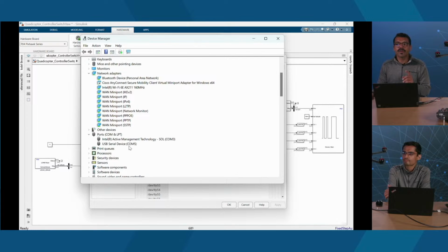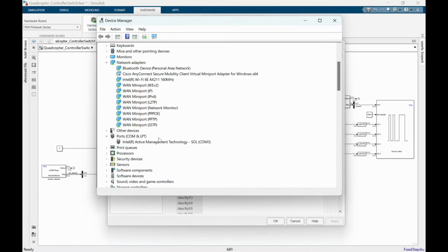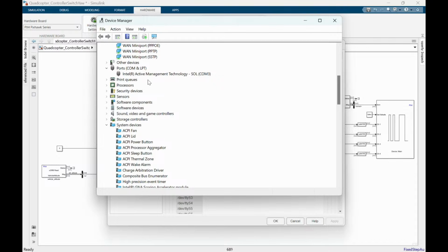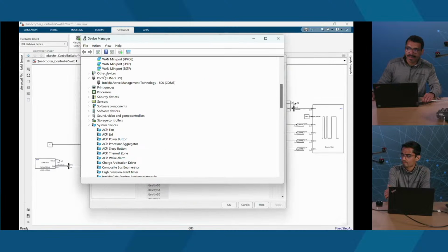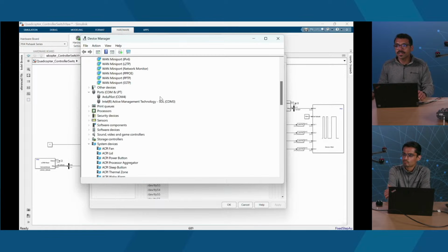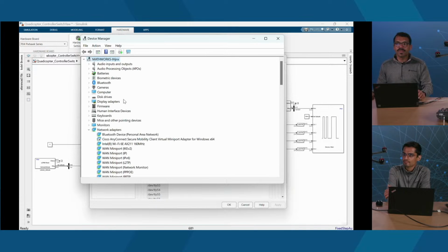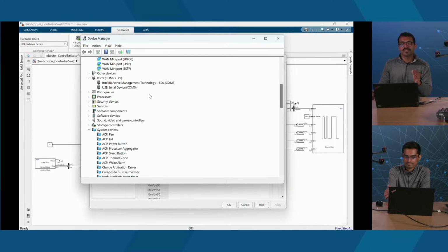With specific autopilots, you'll see that it says USB COM5. I'm going to unplug this right now. It's going to disappear, so now there's nothing there. And then I'm going to go and plug it back. It's going to take a second. It'll refresh. You'll see that, okay, COM4 has shown up. But then as soon as the autopilot starts, it becomes COM5.